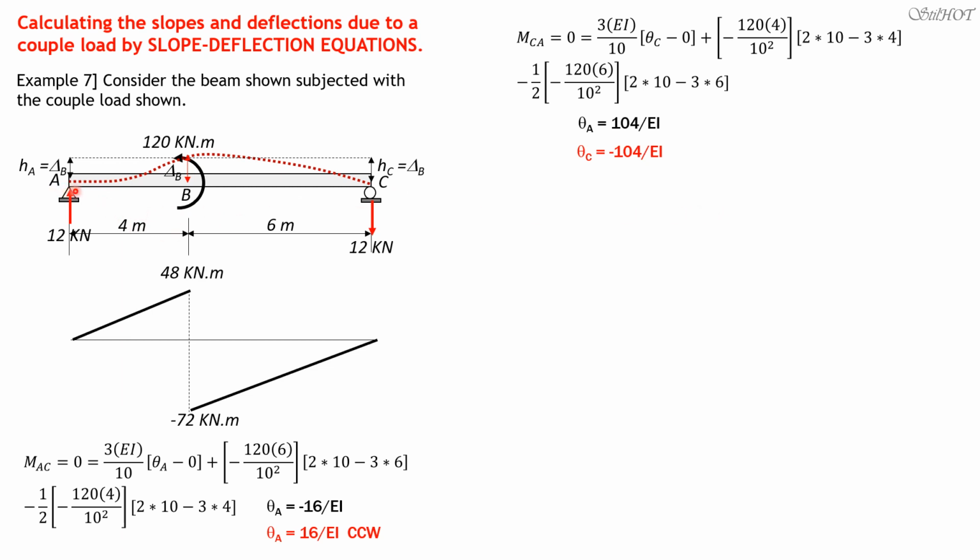And we imagine that B is below, so that the rotation of the chord is clockwise, and there's no issue with our equation here. So 2EI over L, 4, times quantity 2 times theta A, which is based on slope deflection, negative 16 over EI, plus theta B, then minus 3 positive delta, because our assumption is delta is below B, so that the chord AB rotates clockwise, over L, which is 4.